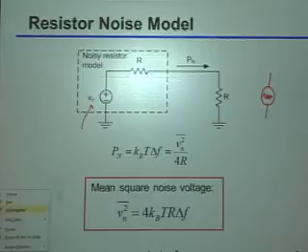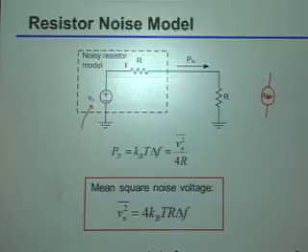Well, so if we think about this, if you guys remember, back in hopefully the very first EE class you took, we always said that if you wanted to extract the maximum power from some source with a given resistance, you should always load it with that same resistance at the output. Okay? So what I'm going to do now is I'm adding this resistance externally, not because there's a real resistor that I want. I'm going to use this resistor to figure out what's the maximum power I can actually get, and therefore to calculate what the variance should actually be.